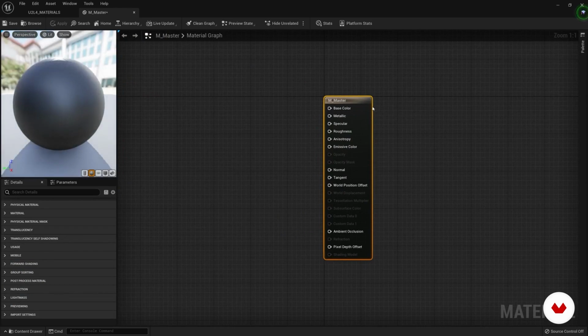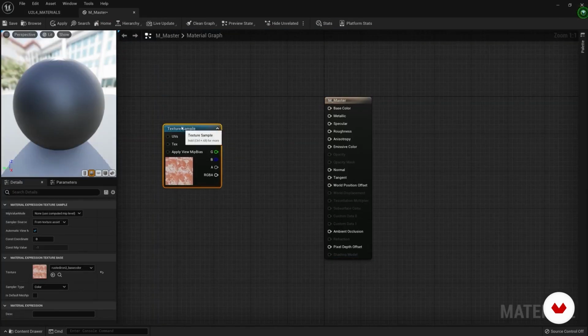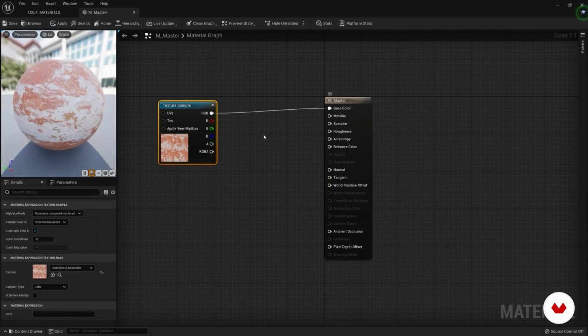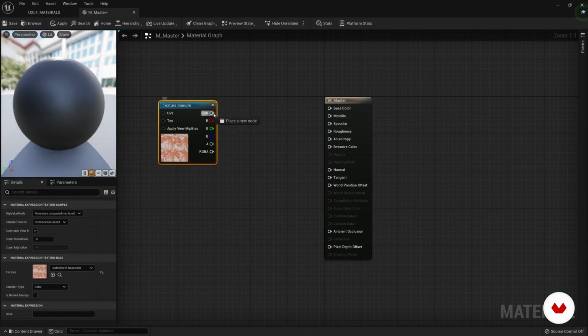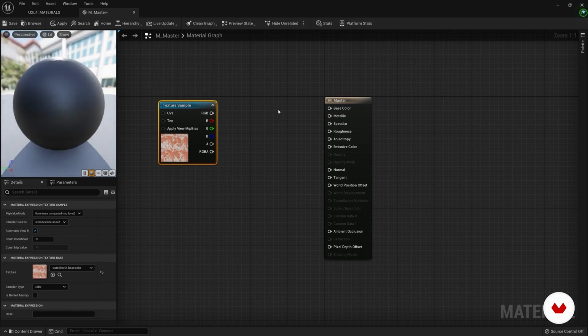The material editor works in nodes. What does it mean? It means that when we add a new resource, maybe a texture, we will add a new node. And the nodes can be connected to each other. Nodes connect with the left mouse button, dragging it, and delete them by holding down the Alt key and click.